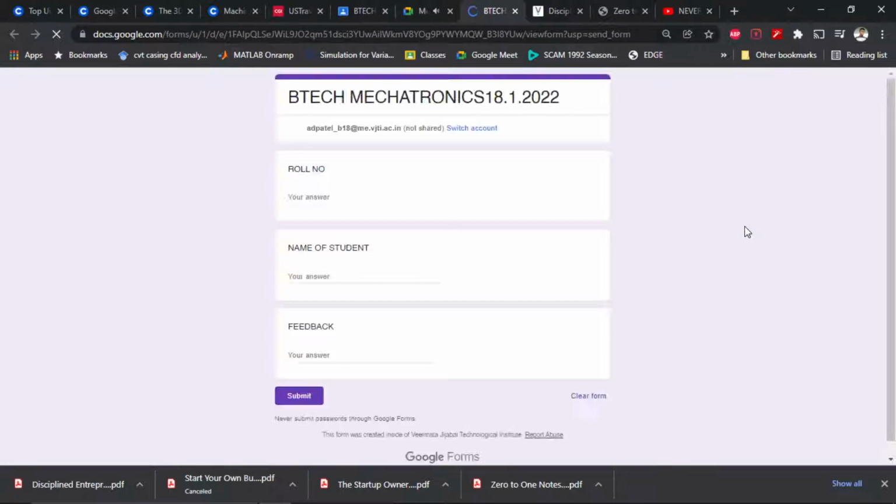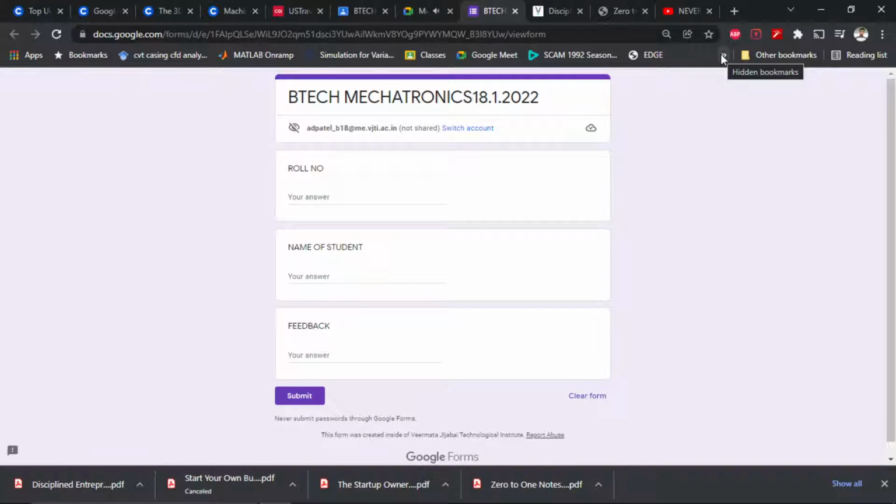So this you can call the shuttle valve. The description for this valve is that it is a 3-port valve with 2 inlets and 1 outlet. We can see 2 inlets as per the direction of the arrow. So in this example, ports 1 and 2 are inlet and port 3 is outlet.